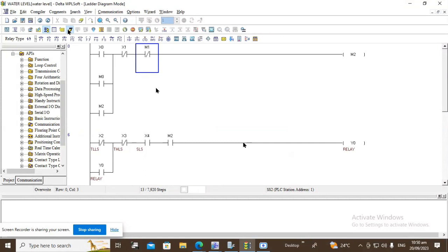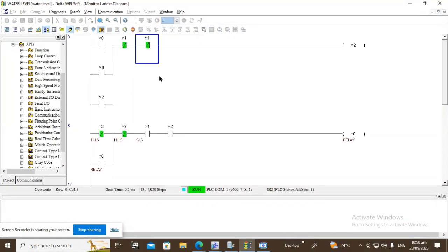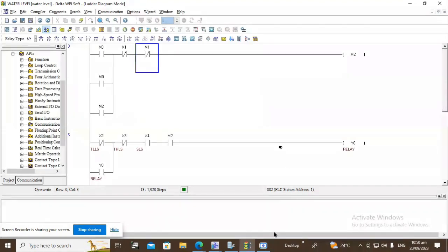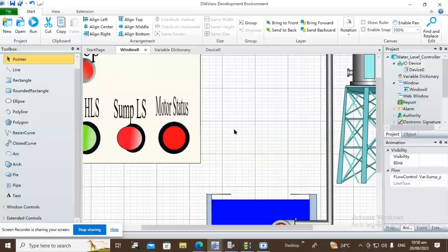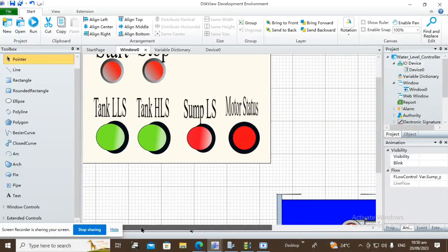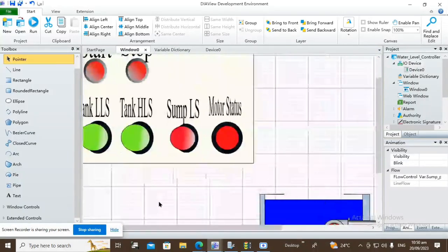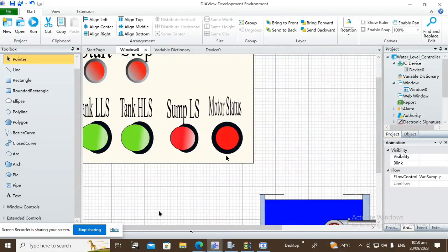Now before going to the SCADA, we can also see if the PLC is working fine. I will just press X naught, which turns on the system based on the sensors. I'll press X1 from the PLC, which turns on the motor itself and the automated system. Now let us go to the SCADA screen. If everything is alright, the status should be straight away available on these sensors.